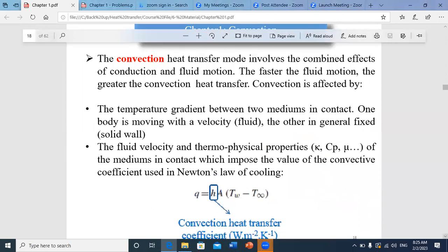Now, as you can see, the process of convection is a little bit more complex than conduction, and it's affected by several parameters. To understand better how we write the convective flux, let us explore together what convection will be affected by. First, of course, the larger the surface area of contact between your surface and your fluid, the larger the heat transfer by convection. So that's why we expect to have the area term within the heat transfer.